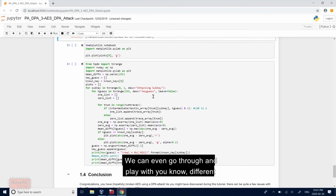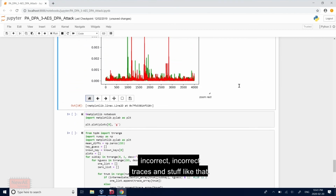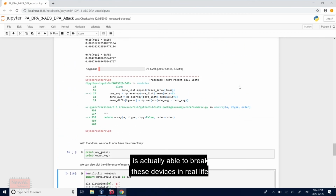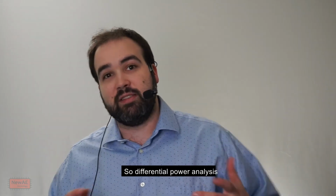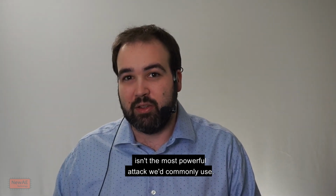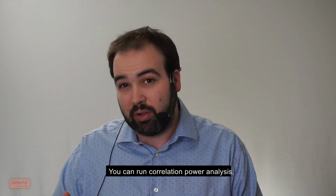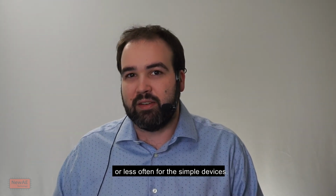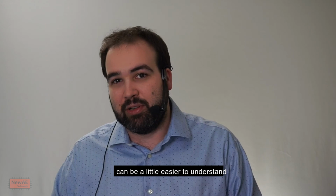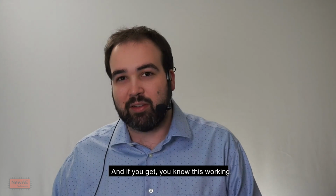We can even go through and play with different incorrect and correct traces and things like that. But the basic idea is just to see how differential power analysis is actually able to break these devices in real life. Differential power analysis isn't the most powerful attack we'd commonly use. There's another attack, correlation power analysis, that's much, much faster. You can often run correlation power analysis in a minute or less for these simple devices. But differential power analysis can be a little easier to understand and to go through how everything works, so you can experiment a little more with that.